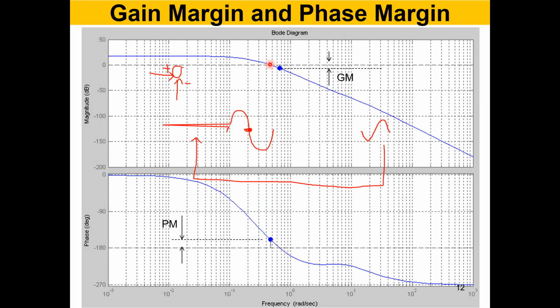And somewhere there, you see the same gain, right? Which means if you have this one, you have the same amplitude here, right? But the phase is different. If you come down from here, you will see the phase at that point. It is not 180 degrees, but you are close to being 180. Okay.